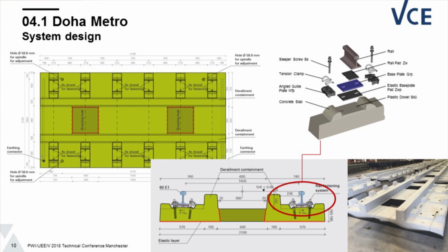Furthermore, we had the need that a lot of cable crossings have to be installed between the system. Therefore, we increased the gap between two adjacent slabs from 40 millimeters, which is the standard for the ÖBB system, to 100 millimeters to allow these cables going through. You see here some of these slabs already fixed in position, just for checking whether the positioning of the slabs is possible.